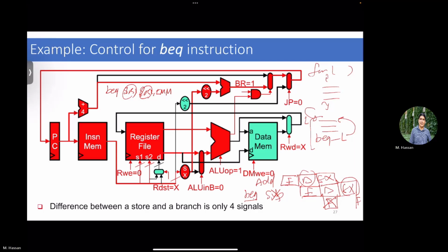Good. So I guess the discussion for the last 10, 15 minutes has just gone down to a pure digital design discussion, right? After we have articulated the high-level design of our logic and data path, how do we design the control path? What we're building here, one by one, if you didn't observe yet, is just the truth table of these 8 signals or 9 signals, right?